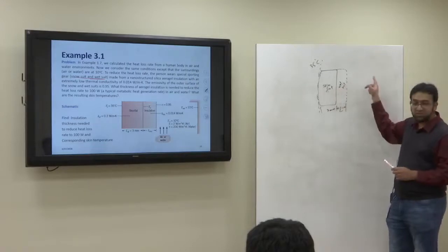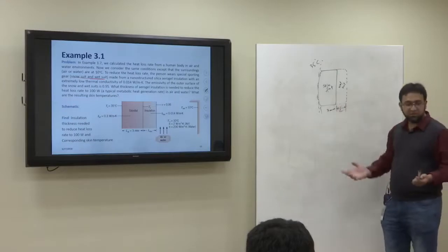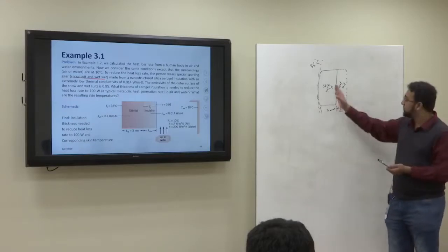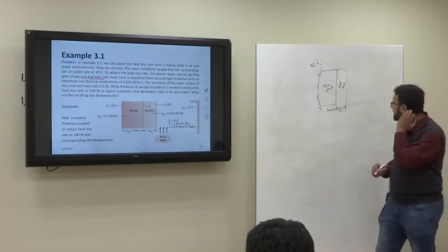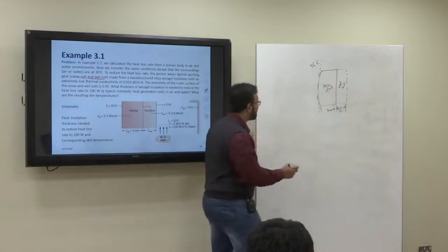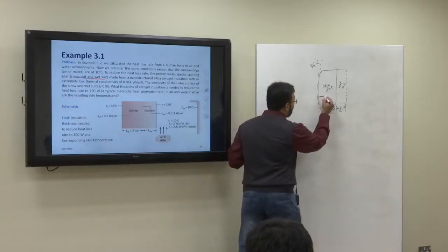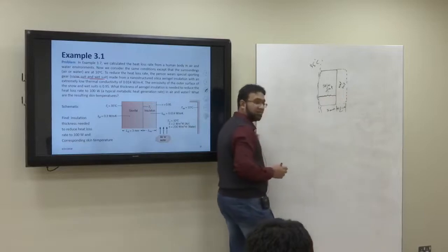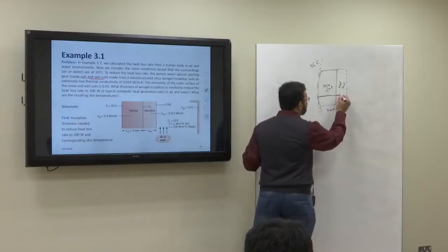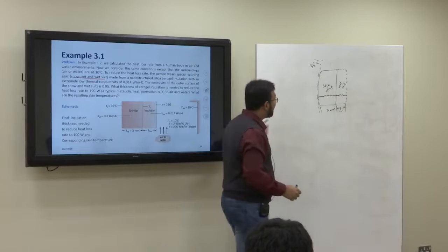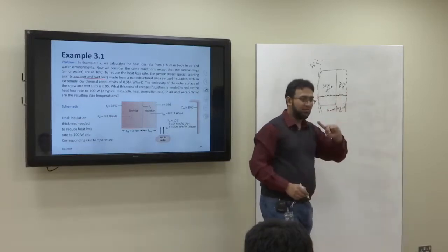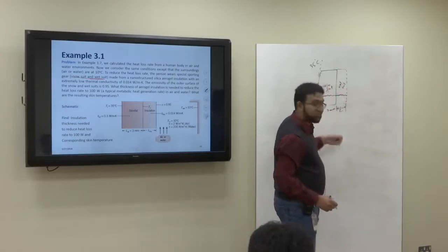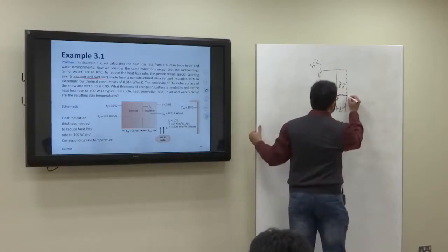Above it, last time there was heat transfer from the skin fat both by convection and radiation. Now again it will be by convection and radiation, but not from the skin but from the wet suit out. So if we draw the thermal circuit, you have a conductive resistance in the skin fat area, then another conductive resistance in the wet suit, and after that a convective resistance and a radiative resistance, and they should be parallel because they are coming from the same temperature surface.